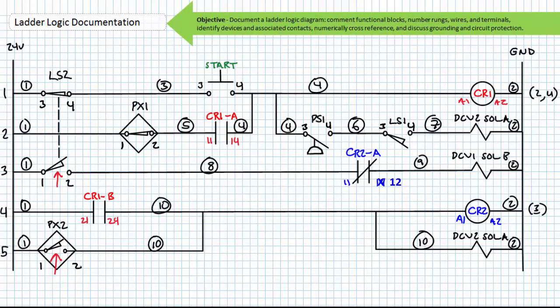If proximity switch 1 and 2 were part of a 3-terminal single-pole double-throw transfer switch device, you might see these terminals called 1, 1, 1, 2, where the 1, 1 terminal is the common and the 1, 2 the normally closed side. Let's assume all solenoids have terminal numbers 1, 2, where terminal 1 respects the required polarity of this DC pilot voltage. Finally, let's ditch the ugly dashed mechanical interlock and numerically reference the mechanically interlocked limit switch 2.